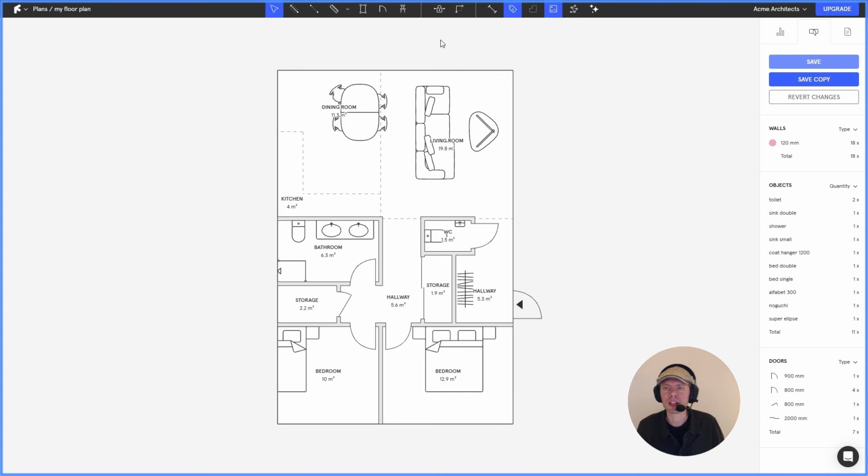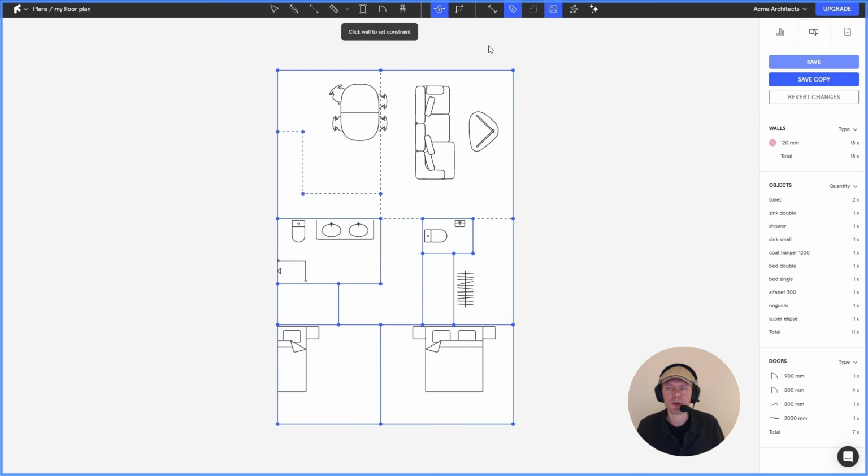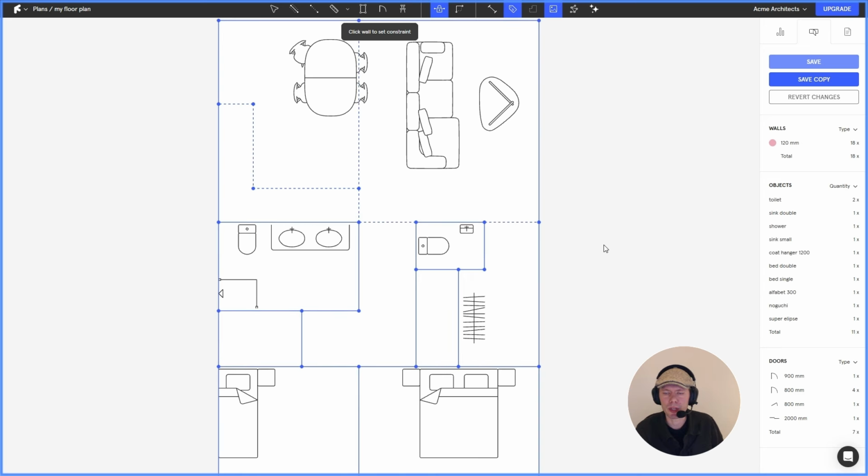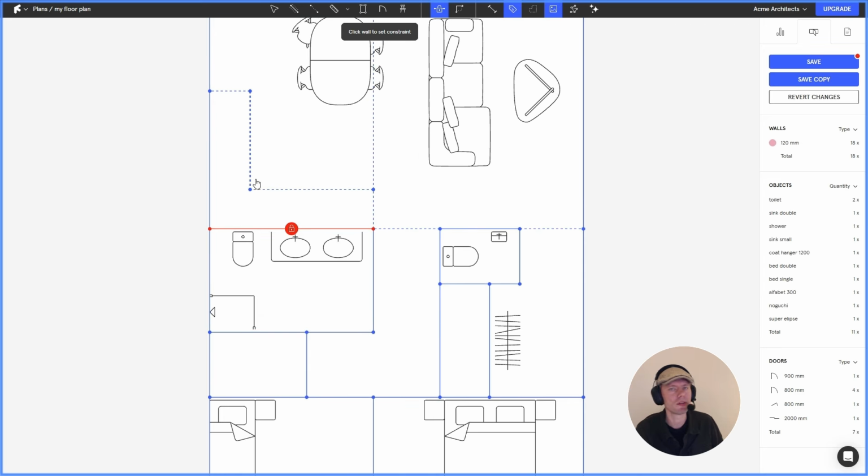So then you can also set constraints by clicking the lock up here to inform Finch on how you would like your design to behave. And in this case, I'm going to work with a bathroom module, so I don't want the size of this one to stretch. My corridors cannot be more narrow, but they are allowed to be wider.